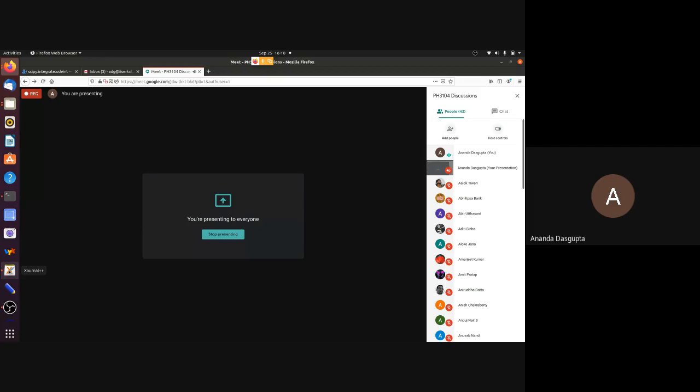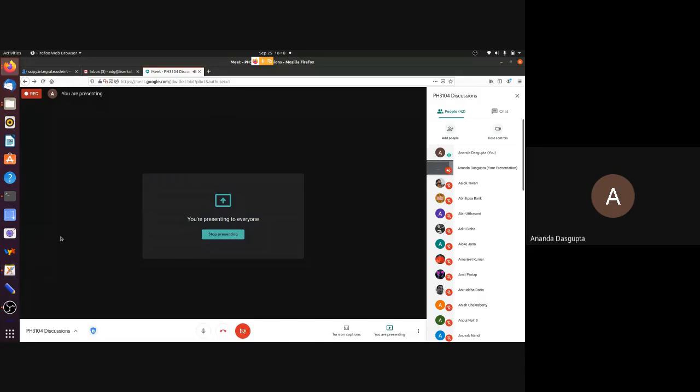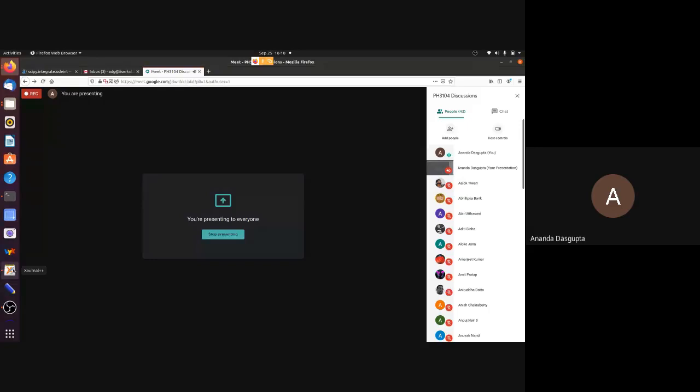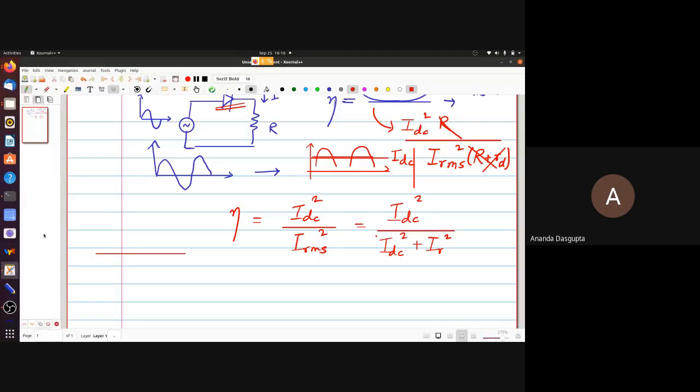Okay. And ultimately, in fact, what you are describing is actually what is used often, or at least was used very extensively in the early days of linear accelerators, when you build particle accelerators with huge voltage, trying to accelerate particles to very high energies. You needed very high voltages, but no. All you needed were high voltages. You didn't need big currents. You needed to establish a large potential difference, and that was essentially done by something called the Cockcroft-Walton circuit, which essentially is a voltage multiplier with many such cells.